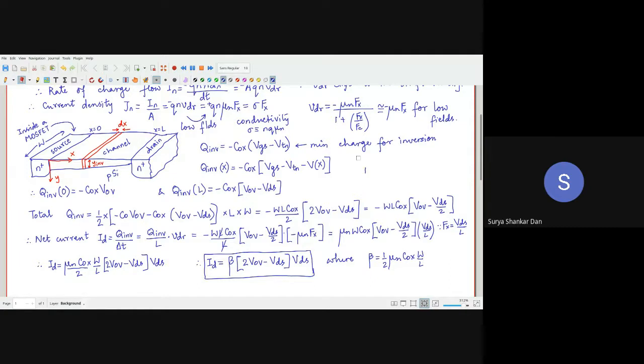Let me just press Control Z. Just see. This is a typical case where you have applied a plus VGS over here. If you are applying a positive one, first you are depleting this part and then you are bringing in the electrons. Then we call it inversion. Why inversion? Because the channel originally was p-type. This was p-type material, right? Now, because of VGS greater than VT for an N MOSFET, the electrons have come to the surface. So you are making the surface as much N-type as the bulk is p-type, remember?